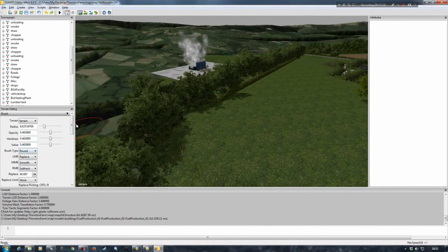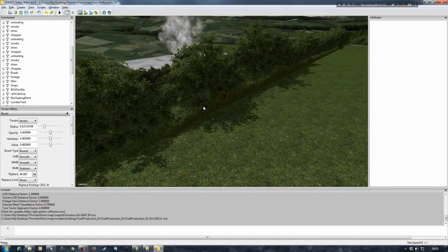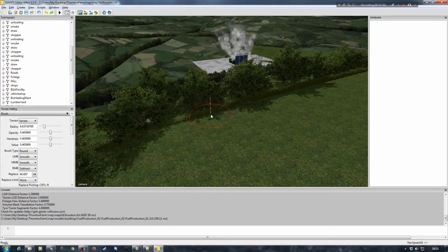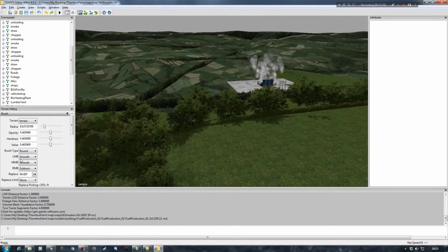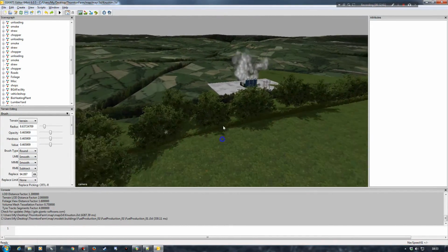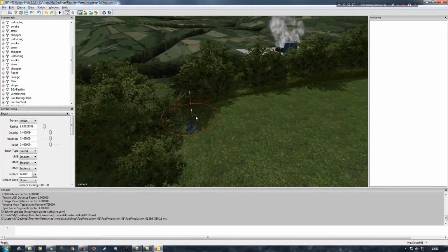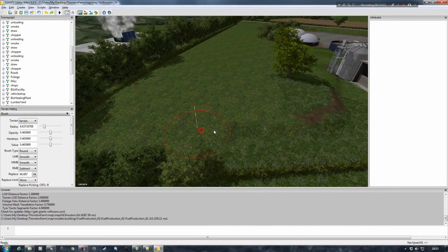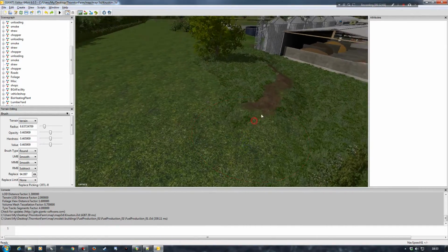And then what I will do is actually change over. So I'm going to change my left mouse button to smooth. I could use my middle mouse button if it worked, but I'm having a bit of issues with my mouse at the moment. So now what I'm going to do is just drag across there with my smoothing tool, using the left mouse button again, so it smooths that edge off. Come around here and smooth this edge off as well, like so.